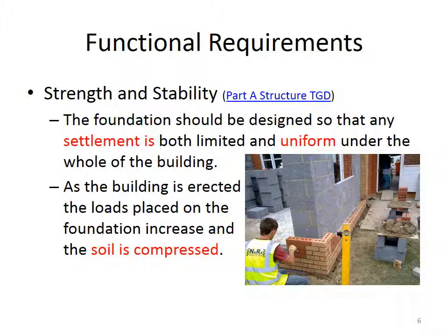There's going to be a certain amount of settlement, a certain amount of movement as all the loads are placed on top of the foundation and the building is constructed. But the idea is when we're designing the foundation that we want that settlement to be limited, so as little settlement as possible, and then also we want it to be uniform, more importantly.